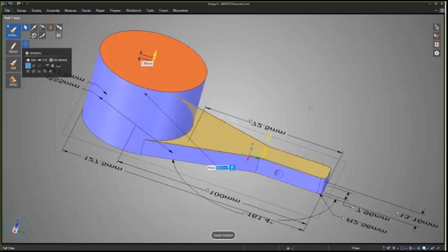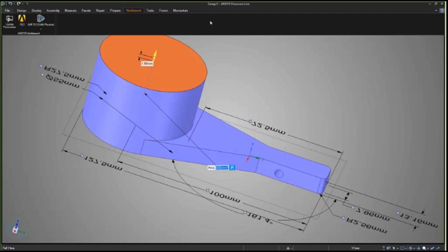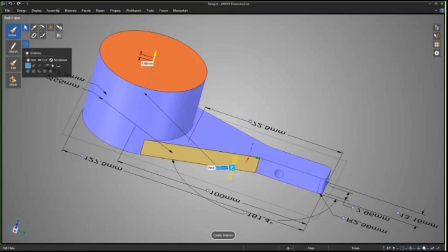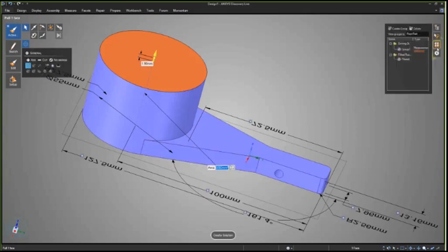And by the way, if you want to do a parametric study here in Discovery Live, or through Workbench and Mechanical and any of the other Ansys products, this P button should be very interesting to you because this P saves parameters. They go in this area over here called groups, where I now have this group, and this parameter is height based on surface area. So this is a pretty advanced parameter there.